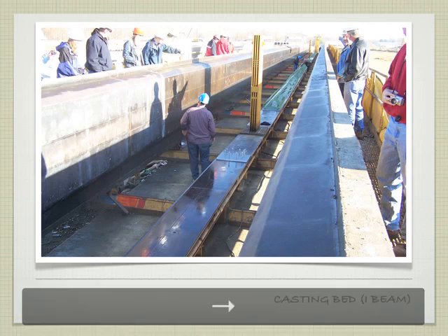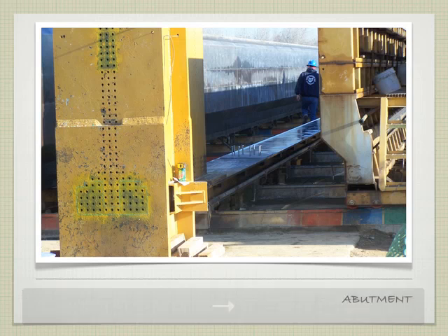Looking again at it, this is that abutment that I was talking about on one end. It's a big steel piece. You've got the little soda can here to give you some scale, which is always good. And so this abutment is where we're going to string all our cables. You can tell that this particular region is where they put the bulk of the cables. It's nicely marked out so that they can figure out where they go. And they're going to string the cables from this end all the way down through that casting bed to the abutment on the other side, so that the cables run all the way through this particular piece.